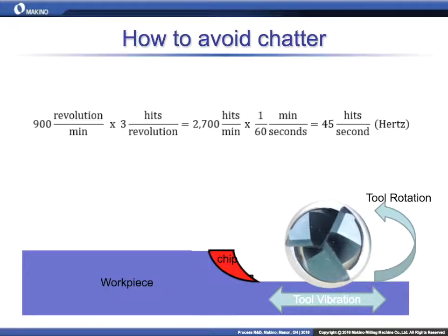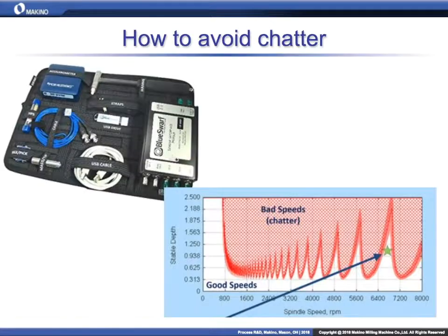Then we've got the other side of this, tool vibration. How do we get that? How do we know what the tool vibrates? So that's difficult. And one of the methods that is probably, I would say, the most popular, is to use impact testing. Sounds a little aggressive. Maybe I've also heard it called tap testing as well. Modal testing, modal analysis. There's a lot of words that can describe it. I'm just trying to throw these out there in case somebody has heard of it and they're like, oh yeah, okay, that's the whatever. Not trying to sound impressive.